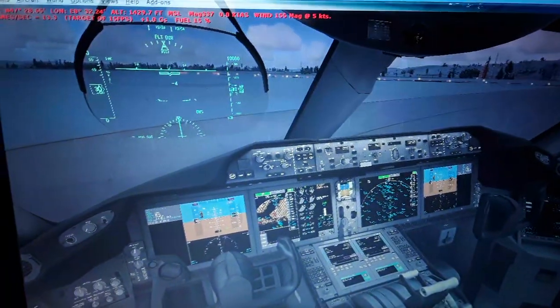We're going to be having an airspeed of about 160, 170 nautical miles per hour or knots for approach and landing. Using the ILS localizer, also the flaps 25 to 30 degrees, the thrust set in the engine 60 or 70%, and also pitch attitude of 9 degrees or less, and the landing gear extended.